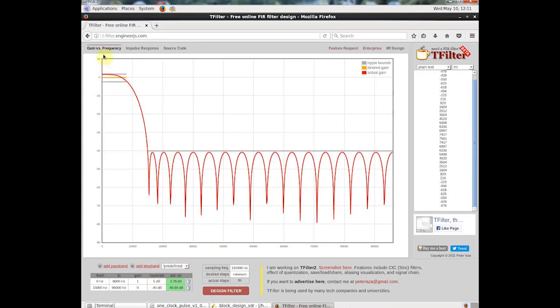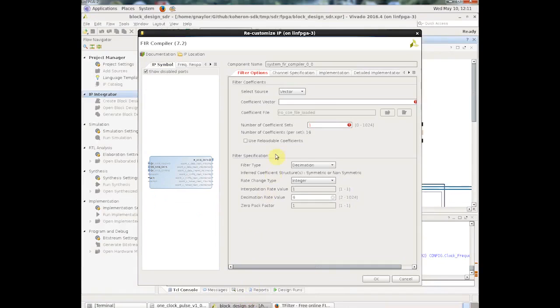So, as I say, you can play around with this to get whatever attenuation you want, and whatever flatness performance you want in the passband and width, but the main purpose of this is to take out the lobes that we'll have generated with the CIC filter. So, here are the coefficients here. Now we've chosen int here, so we've got integer values. So we're going to copy these into the Vivado window. So copy. But to get them in here we need to separate them by commas.